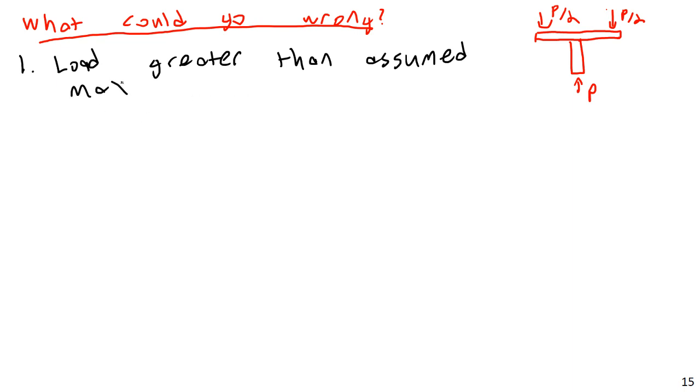So in other words, I went to the mechanic and said, what is the biggest car you've ever lifted into your shop, or ever fixed up in your shop? And the mechanic said it was so and so, and I designed for the dead weight of that car. But let's think of how that load might be exceeded. The first obvious one would be, what if somebody rolls into the shop with a car that's heavier than the one the mechanic has ever seen before? There's always a heavier car out there.